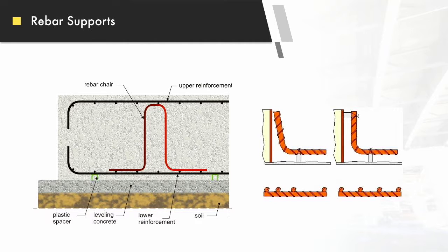This picture over here is showing like up against the form, they'll put the bottom chairs in, but then they won't chair up against their form, and so your clearances on your walls a lot of time are not achieved, and they'll get it up, you'll go back to do your inspection, and then instead of having your 2 inches or whatever is called out in the plans, you don't have your proper clearance, and then they want to fight you to get down in there because they have to undo rebar, get down in there, chair it out.